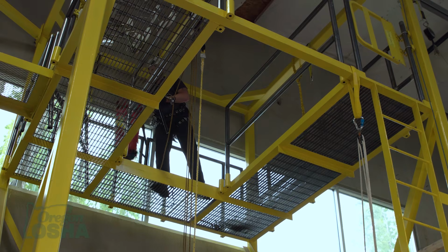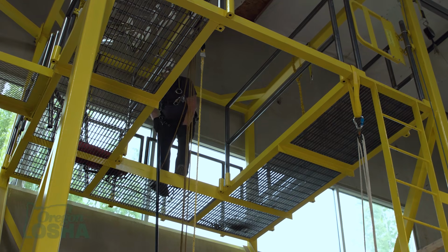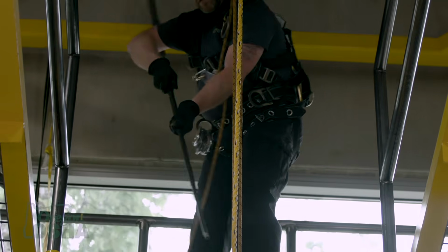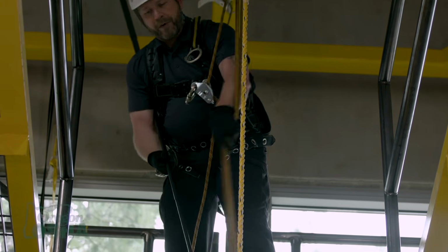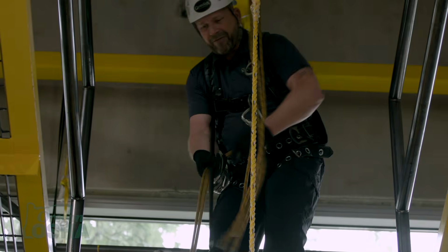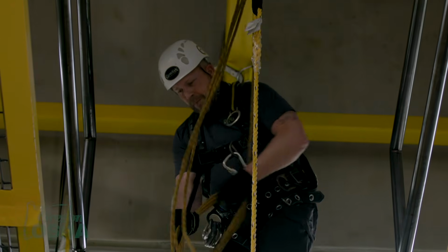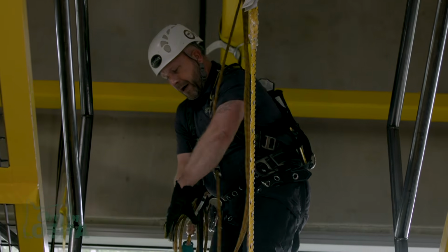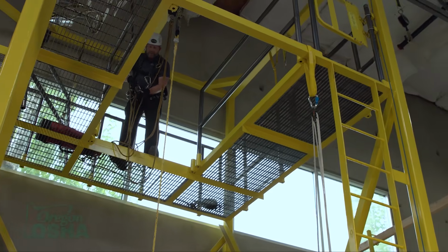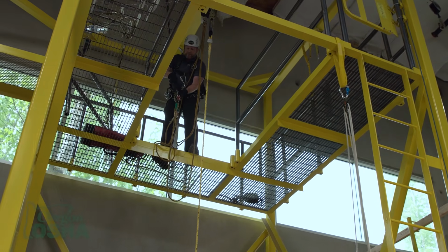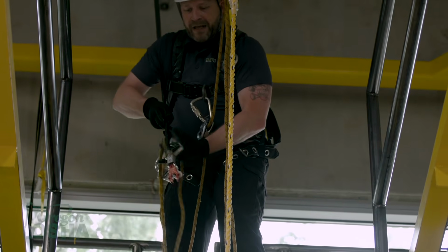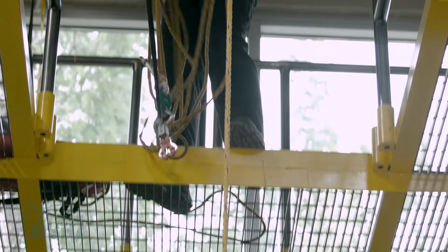If we're doing our fall protection well, we're going to be prepared for all kinds of scenarios. Now once I've measured out the rope, grab my remote pole like this, get it pulled through. And then we're just going to bring the rope up here and get it connected. Again, this is a system. There's a lot of different systems available. But you can see where if you're not practiced, you're not aware of what's going on, or you get in a rush, this can go badly. Because if I drop any of this stuff and I can't retrieve it, my rescue capabilities have just significantly changed.